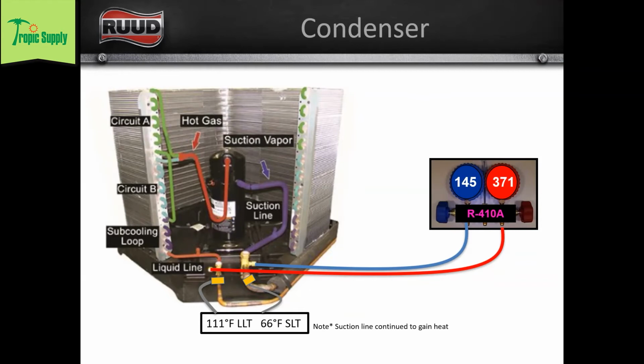I see that the suction line temperature on this unit is 66. Is there a limit to that suction line temperature where it can cause harm to the compressor? Well, the compressor is cooled by the refrigerant, and it won't necessarily harm it, but it will open the limit, right? There's a thermal switch in that compressor, and if the compressor gets too hot, that limit switch is going to open. Most of the time it's just a little bimetal switch, and if we open and close that safety a number of times, it can fail.